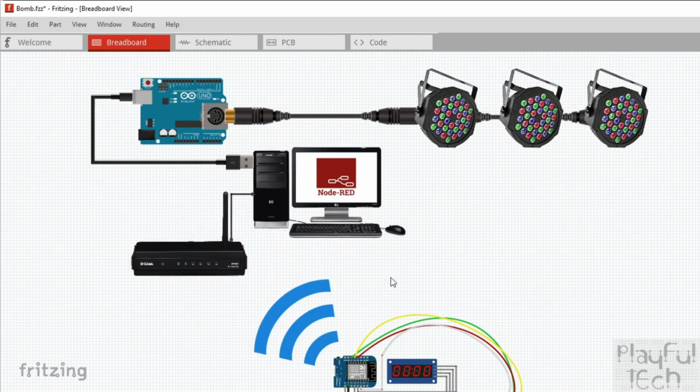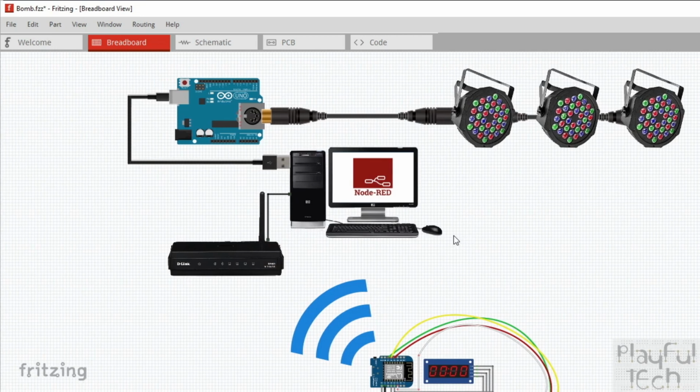This is connected to the same network that my Wemos is connecting to. So that's going to enable the Wemos to publish MQTT messages to the broker that's running on this server, that Mosquitto broker, which is part of Node-RED. And then I'm using the USB cable to connect to the UNO here. So this is exactly the same way that you'd connect an UNO if you wanted to upload code to it, for example, using the Arduino IDE, or if you wanted to monitor the serial monitor connection to debug information about what's running with the code.